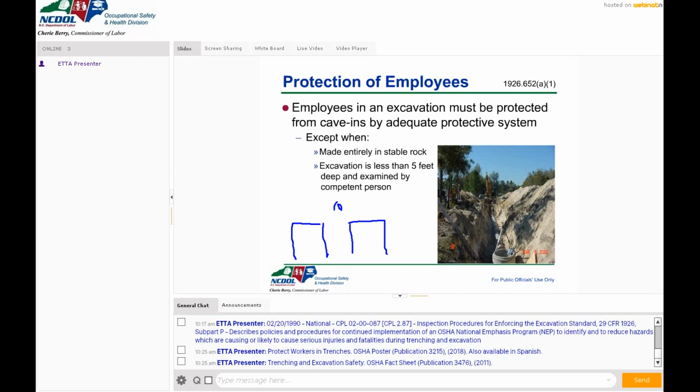All right, Mr. Terry said 20 feet. Does anybody go along with what he says? All right, we're going, say, 6 feet deep. I didn't add that input in on it, but just throw that out there. Mr. Zachary pointed out the angle. For every foot down, we are now required to go a foot and a half back. So that 10 foot can turn into a very, very big hole. There's where you can do that little calculation in your head.